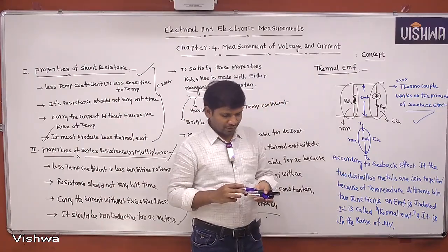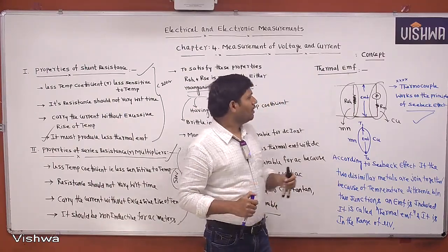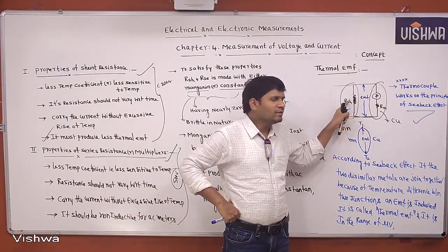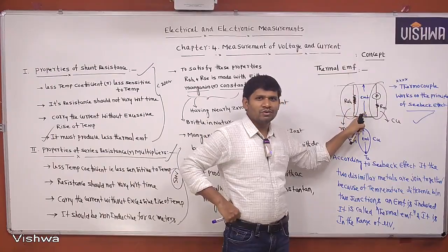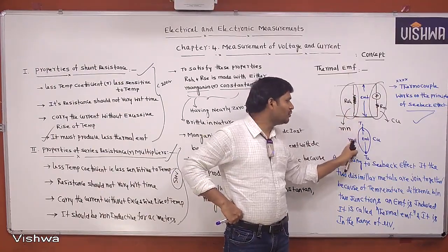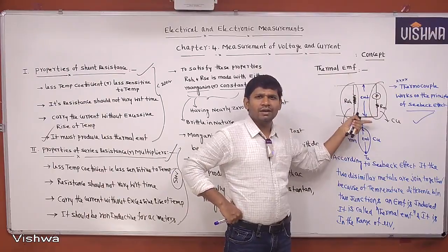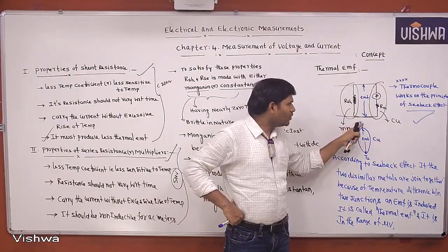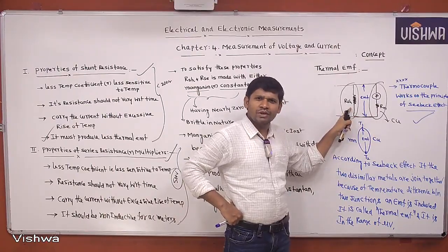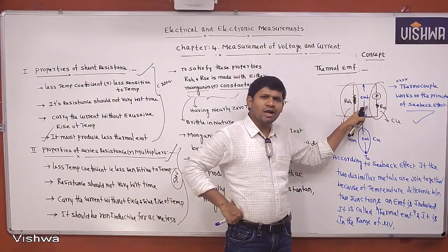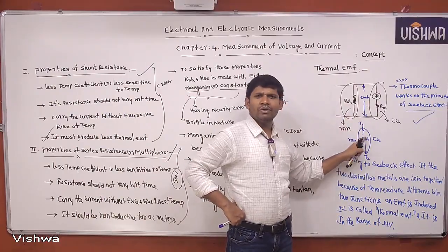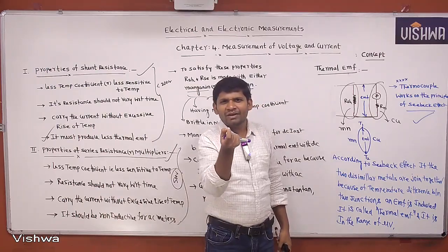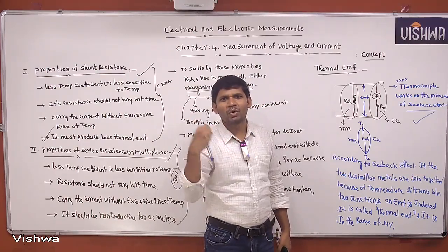But you may have one doubt here, sir. Because the shunt resistance is made with manganese, thermal EMF is produced, and because of two dissimilar metals it gives a wrong reading. Why not directly use copper shunts? Then this is copper and this is copper, similar materials, no EMF, no error. That is meaningless, because the thermal EMF effect is very less and negligible. It is in microvolts.